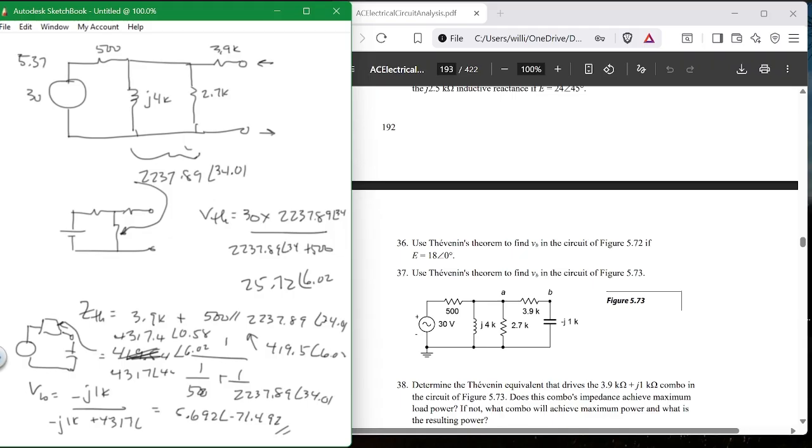You measure the DC coil resistance of the inductor by using an ohm meter on your old DMM, measuring across it to get the resistance of the coil, which is added to the resistance of R. But really, you don't worry about it. You just measure it, but you don't do anything more with it.